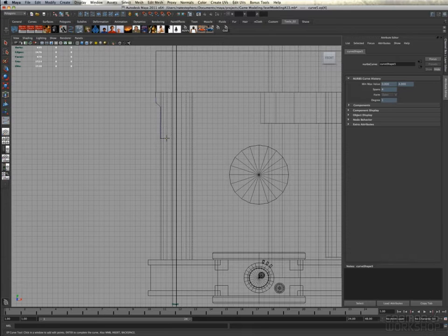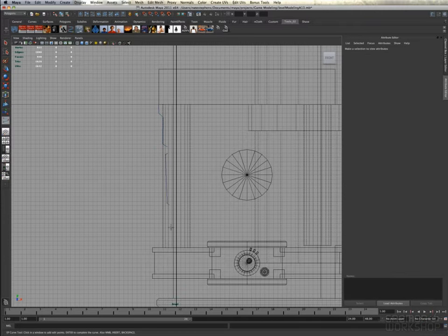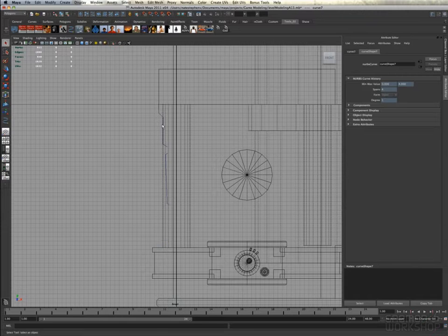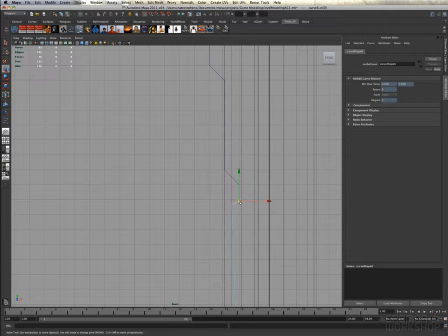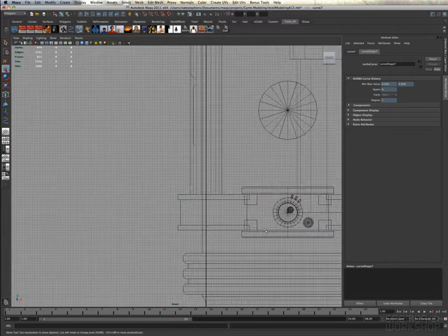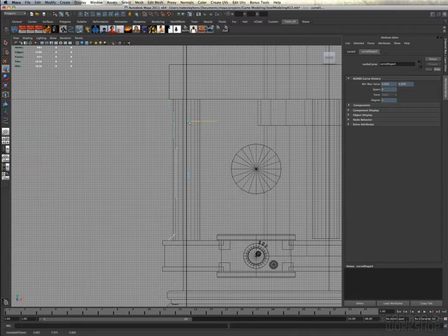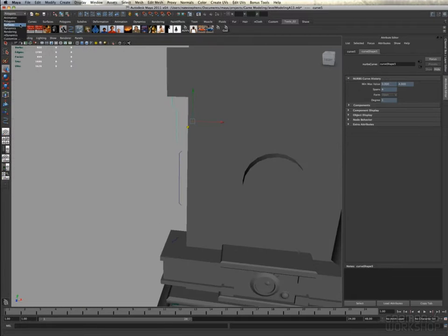And you can see the tools I'm using. Right now I'm drawing out a curve. This one I'm not even really snapping to the grid, just trying to get the shapes in. It's almost like painting. And then after the fact I'll go in and snap it to whatever the closest grid point was. And once I have a shape I like, if I'm going to revolve this, I'll put the pivot point in an appropriate spot and then use the revolve function.